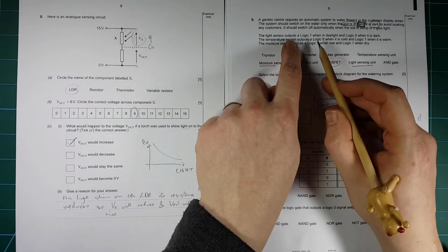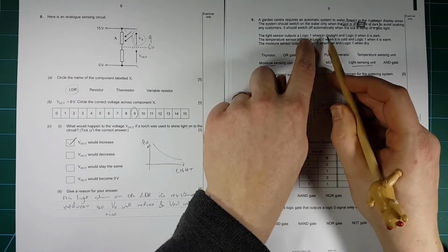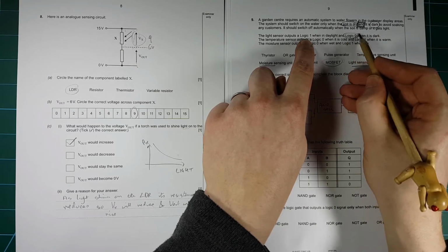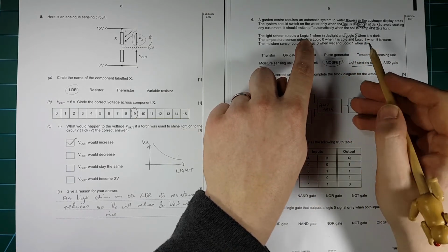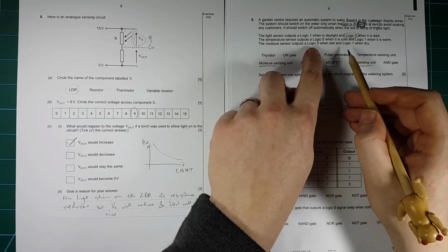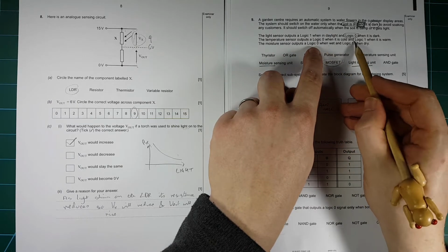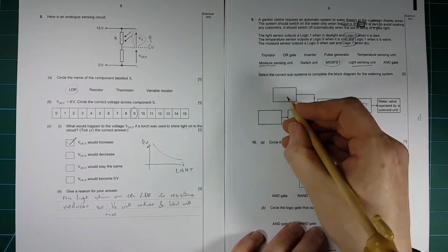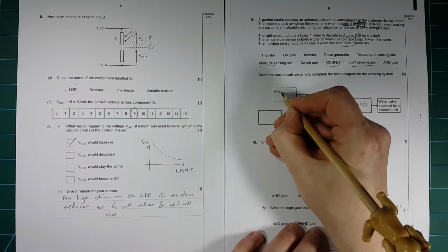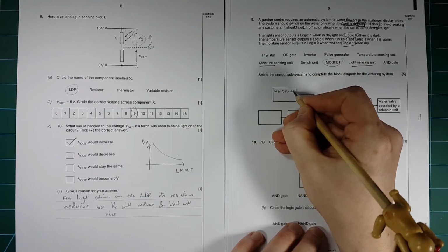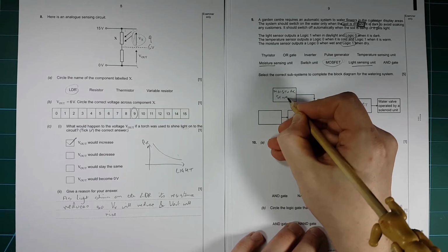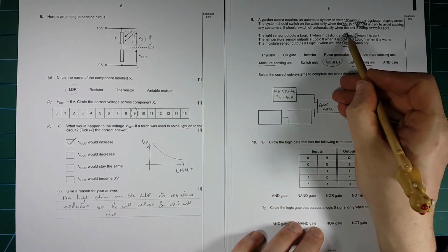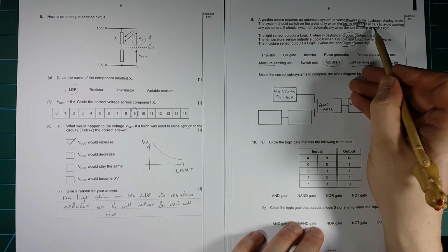And we're going to think here. So when the light sensor is 1, when it's daylight, we want it to be dark. So we want it to be a logical 0 when it's dark. The moisture sensor is a 0 when it's wet and 1 when it's dry. So we can put the moisture sensor straight in here, and this one's going to give us the logical 0 when we want it to turn on.